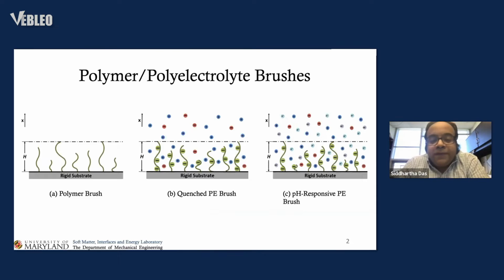So there are polymers. Now, these polymers occupy a special kind of structure, like the bristles of the brushes, when they are densely grafted to a substrate, and hence they want to avoid each other, and hence the only way they could go is to stretch away from the grafting surface, and hence they occupy this kind of brush-like structure.